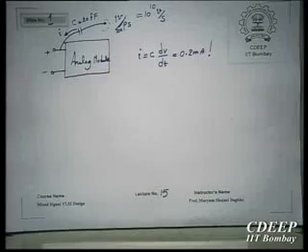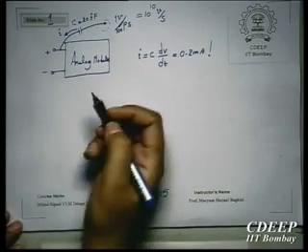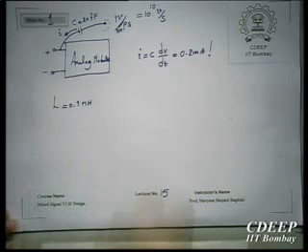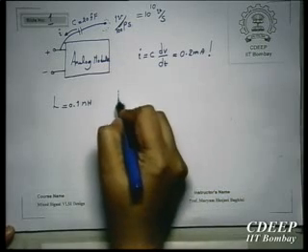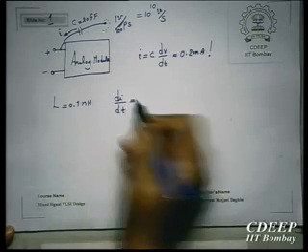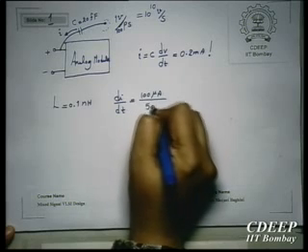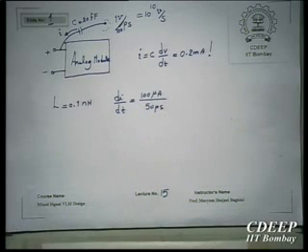Now the question is, why only capacitive coupling? We can have inductive coupling, just the dual of this effect. Why in CMOS usually people are talking about capacitive coupling? Why not inductive coupling? So consider, suppose I have a parasitic inductor of 0.1 nanohenry. Again, I have considered a large value. And suppose this experiences a di upon dt of, again a typical value, 100 microamp in 50 picosecond. 100 microamp is quite typical for a digital circuit in 50 picosecond.